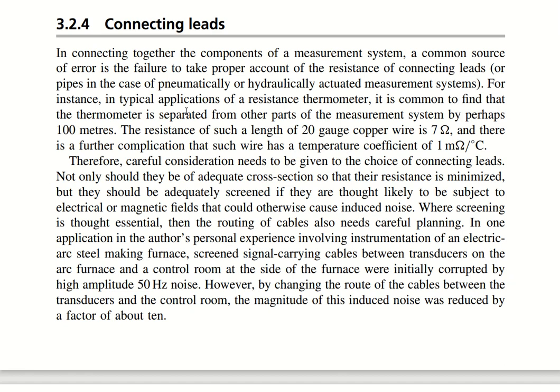So careful consideration is required in the choice of the connection leads, and not only should they be of adequate cross section so that the resistance is minimized, but they should also be adequately screened if they are thought likely to be subject to electrical or magnetic fields that could otherwise cause induced noise, right? So where screening is thought essential, then the routing of the cables also requires careful planning,